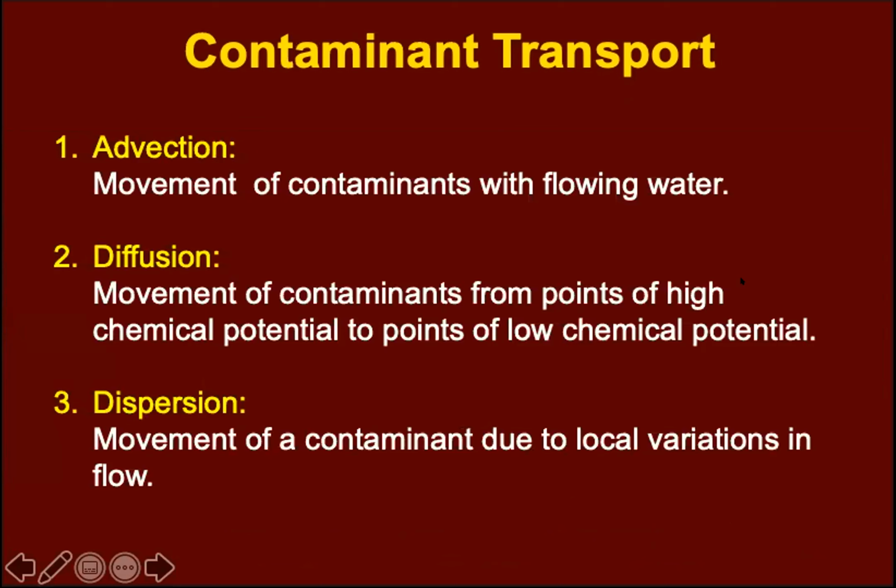So I will focus on contaminant transport that will occur at the base of the landfill. This type of contaminant transport can occur through different means, which includes advection, diffusion, and dispersion. When I'm saying the phrase contaminant transport, I'm usually referring to all of these three.